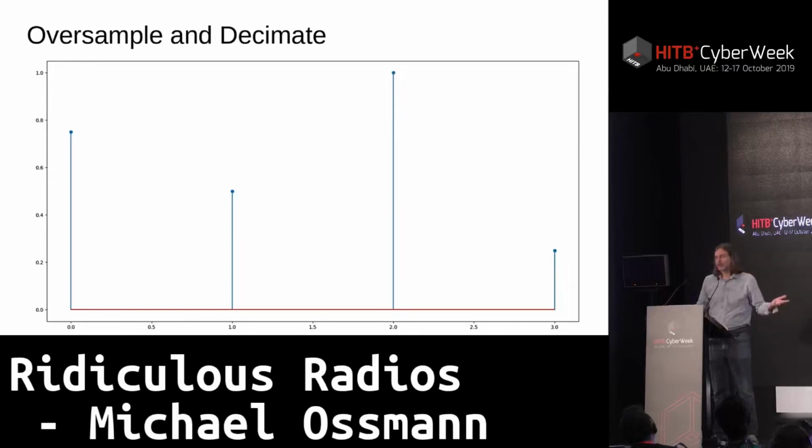But the end result is basically the same. You filter and decimate. Decimate means reduce the sample rate or throw out samples, except you don't actually just discard them completely. You combine them together into a smaller number of samples that have more bits per sample. And if you do this, then you gain dynamic range. You gain the ability to discern weak signals.